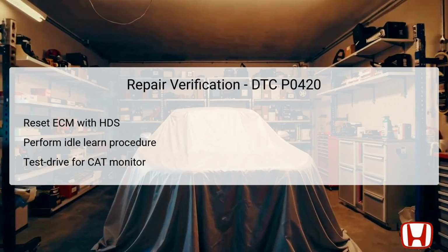After addressing any issues indicated by the diagnostics, repair verification is critical to ensure that the vehicle components are functioning properly. Begin this verification by turning the ignition to the on position and resetting the engine control module, ECM, using the HDS. This reset helps to clear any historical data and recalibrates the system.